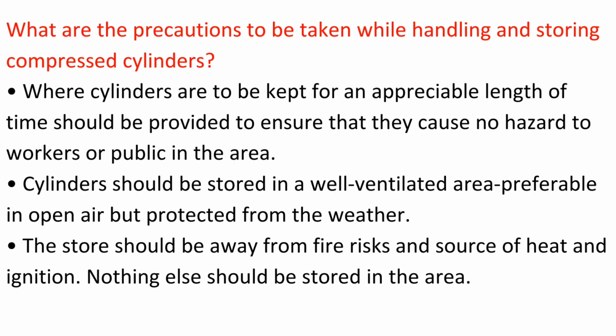Question. What are the precautions to be taken while handling and storing compressed cylinders? Answer. Where cylinders are to be kept for an appreciable length of time, storage should be provided to ensure that they cause no hazard to workers or public in the area. Cylinders should be stored in a well-ventilated area, preferably in open air but protected from the weather. The store should be away from fire risks and sources of heat and ignition. Nothing else should be stored in the area.